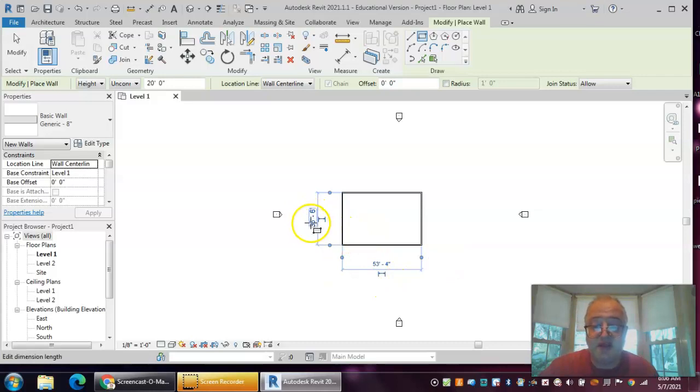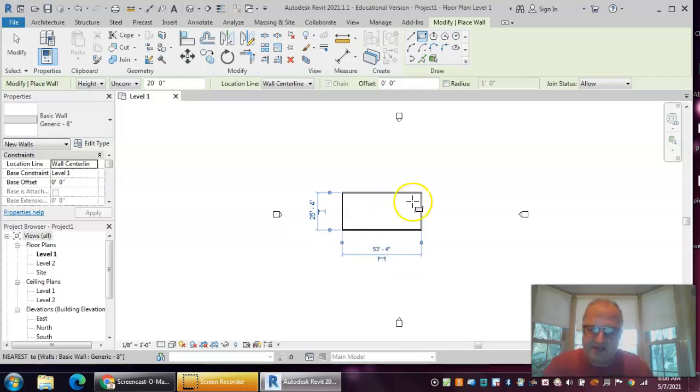So now I can set this one, and on our print, we see that it actually measures 25 feet, 4 inches. Part of what we're doing here isn't just learning how to draw these walls in Revit, but it's also designed to give us an idea of how to read these prints while we're in there too. All right, so there's my external walls.